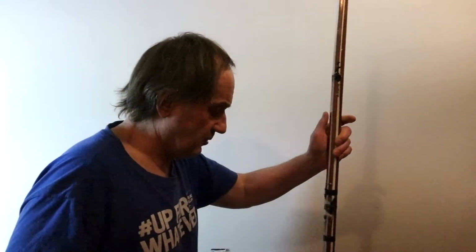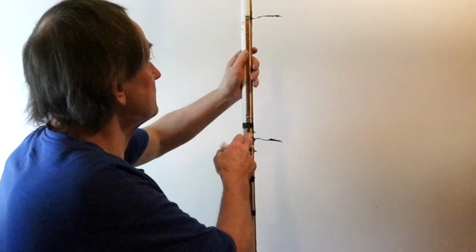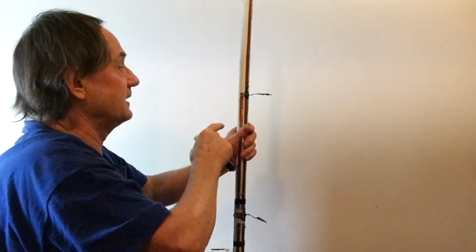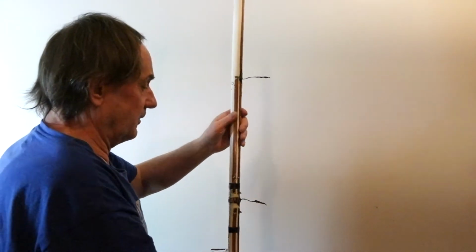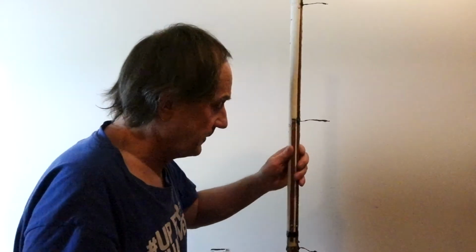However, I've been more detailed and nuanced in what I do. I built this thermistor array. There's 5 thermistors mounted on this pole, separated by 30 centimeters. And a thermistor is a solid state device whose resistance is a strong function of temperature. So by measuring the resistance and knowing the relationship between resistance and temperature, you can get what the temperature is.